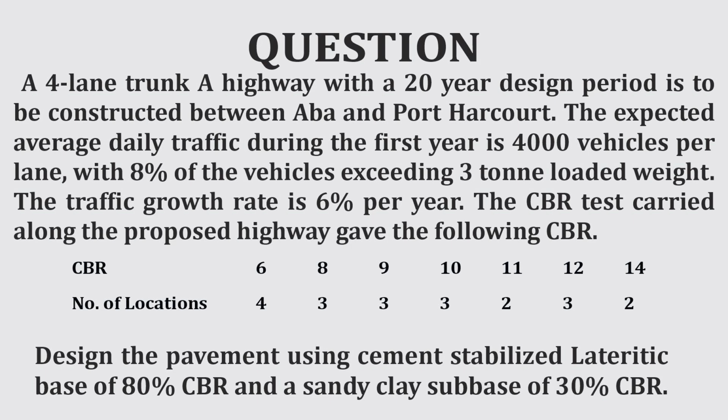and Port Harcourt. The expected average daily traffic during the first year is 4,000 vehicles per lane, with 8% of the vehicles exceeding 3 tons loaded weight. The traffic growth rate is 6% per year. The CBR test carried along the proposed highway gave the following CBR.